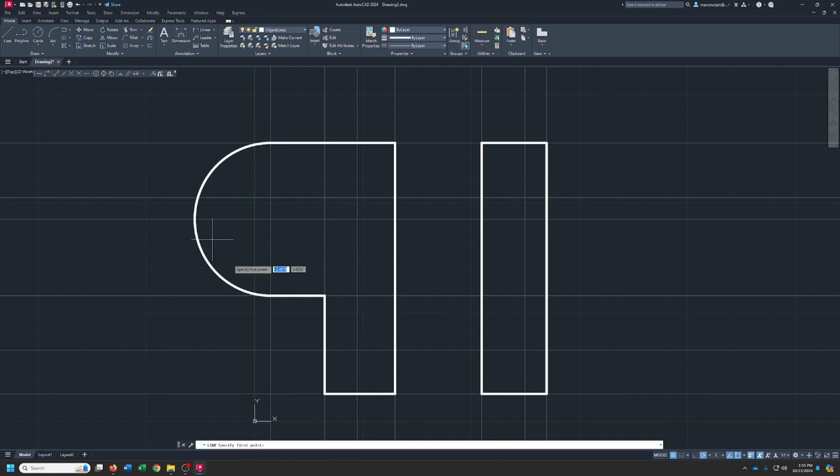We know we've got a line coming through here if you look at the thing. So we'll bring one there. This one is coming up 30 degrees, so make sure Pac-Man is set to 30. Pick line, start there, go 30 degrees right there. Now we can trim here and here.